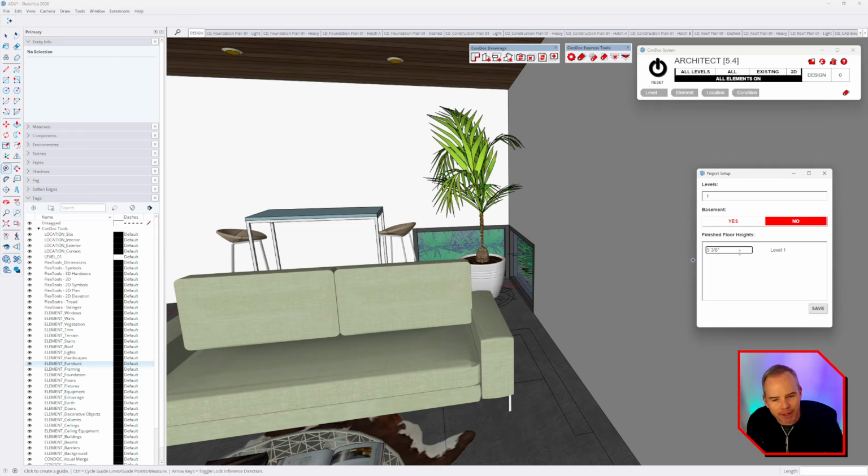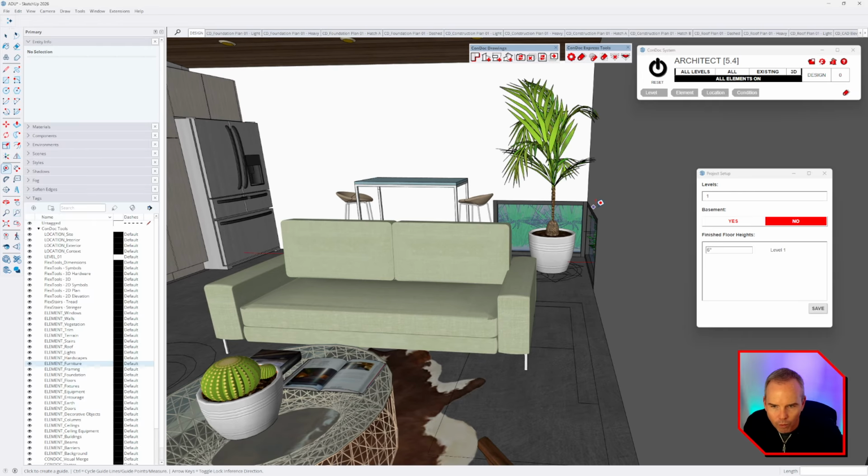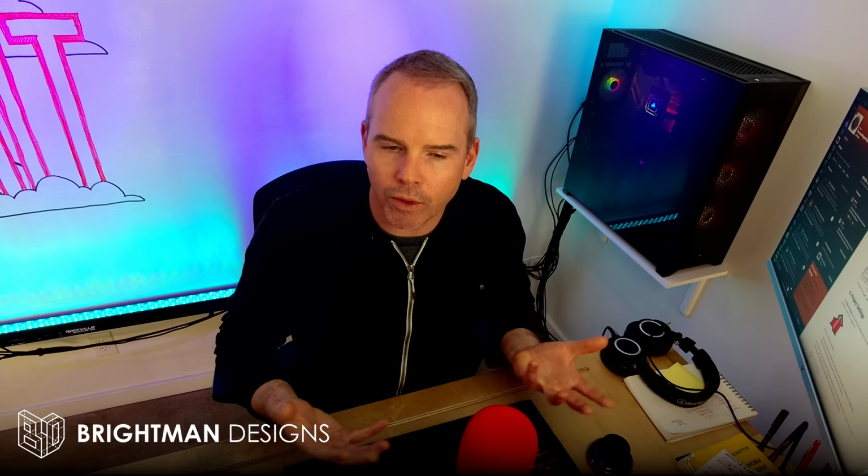But in my opinion, I would just call it 6 inches and move on from there, because all we're doing is, when we drop the section cut for each plan, we're just measuring 6 inches up off the origin for level 1. And then based on the settings in the configurator, we're going to jump up 4 feet to cut that plan. All of this can be modified once you create the plans, you could adjust your section plane, but it's nice just to get it close.